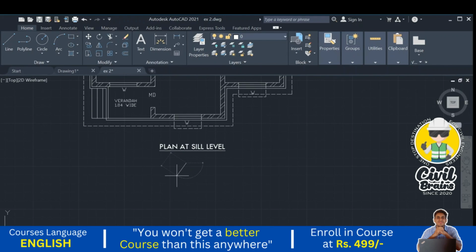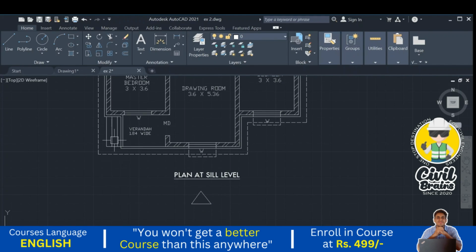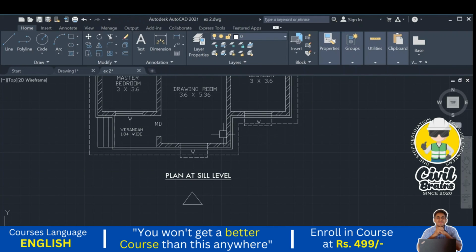So we are standing in this direction, facing like this. If you stand here, the steps and this window are visible. This door will not be visible because it is in the side elevation, not in the front. And this side wall will not be visible, only this corner line, this window and this wall, this corner, this slab projection and these steps. So these things will be visible in the front elevation, correct?